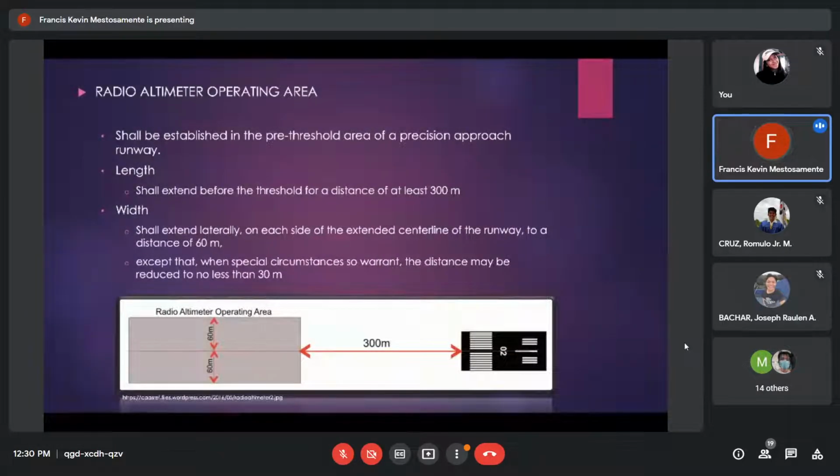Actually, if you operate an aircraft, makikita nyo na yung laki ng itinatalon ng altimeter when you change yung pressure sa sea level. So magkakaiba tayo ng actual pressure associated per airport, kaya kinukuha to every approach, takeoff and landing. And if you change yung QNH on the aircraft, makikita nyo na ang laki ng tinatalon ng altimeter in terms of the static pressure. Kaya for the safety of the operation, we use this radio altimeter to provide exact altitude for landing aircraft. Ang function ng radio altimeter, nagbabounce back siya ng signal from the ground and kinocompute ng instrument getting back on the aircraft to provide an exact altitude.